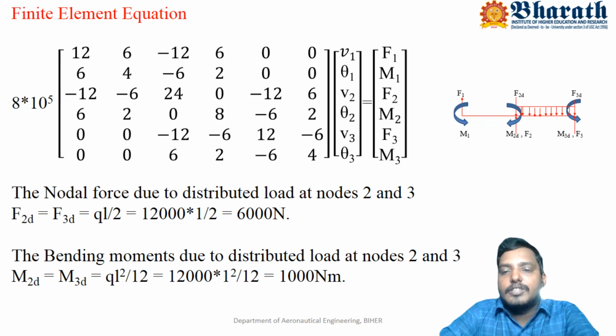The one is a fixed support. Then if you go for nodal location 2, it is subject to a roller support. It will offer one reactive force that will be F2. Then this F2 2D, then M2 2D, will be influenced by your uniformly distributed load. That means the distributed load as well as distributed moment.